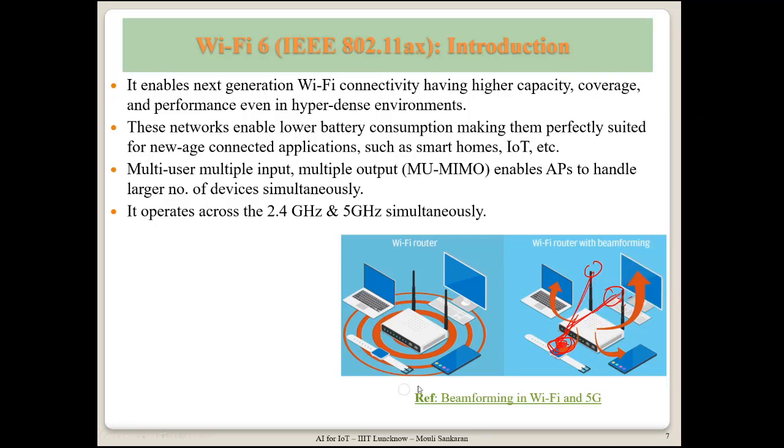They change the phase of the signal, like a 90-degree phase shift, shifted like this. This is the phase phi. So they change the phase of the signal they are transmitting based on the distance of the device and the way they are positioned, so that the transmitted signals add up on receiving. So they get more energy. Even if you're transmitting a weaker signal, they get added up and the receiver sees more energy on receiving it.